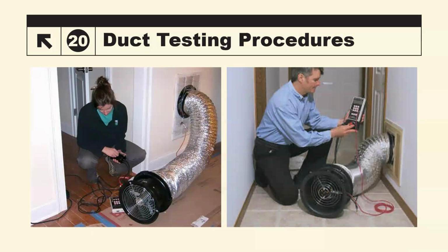And then, of course, also at post-construction, this is kind of what it looks like here. This is during the final stage of construction. You're actually going in and taping things up. But testing at this stage usually will ensure that if there's any damage done during phases like the electrical phase, the painting stage, the attic insulation phase, somebody tripped over it, somebody pulled it loose, something's happened to it between rough-in all the way to final, you're going to catch this and fix it.